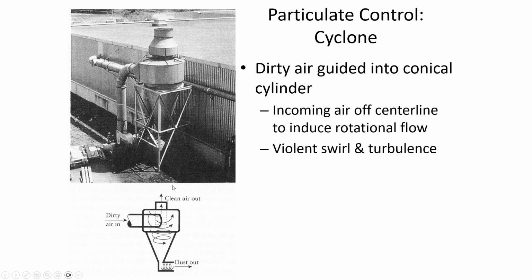So it's not as effective as bag filters or electrostatic precipitators, but in this case, there's literally no moving parts, no electricity being consumed. You're just basically making use of physics and the fact that what it's basically doing is getting the dust to settle. And if you have the dust and you stop it, the particles will settle down. But this is enhancing the acceleration. Instead of just relying on gravitational acceleration, if it's going in a circle, then that induces a centripetal acceleration that forces the dust particles to the edge of the cyclone.